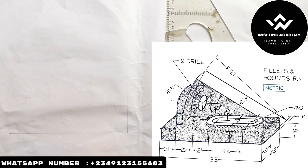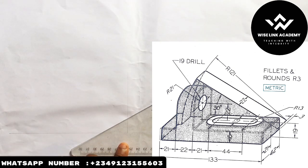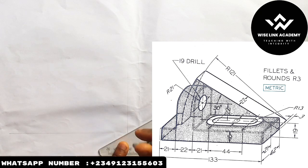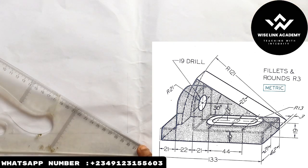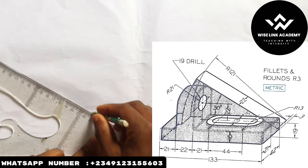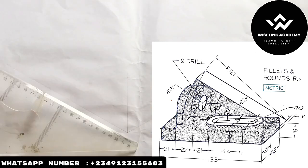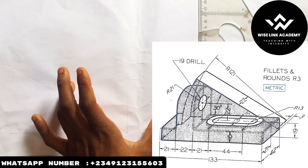When you are done with this, you take your t-square, incline at 30 degrees. I'll draw 30 degrees this way. Also, I'll take it the other way around, and I'll also draw 30 degrees this way. Alright, this is what we refer to as the isometric axis.